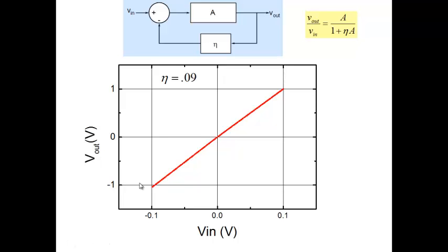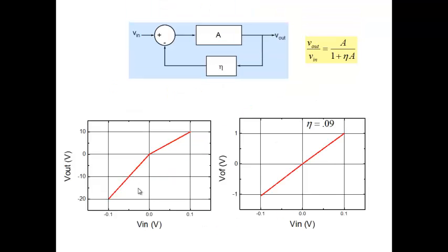How has this happened? So let's put both of them together. How has my overall amplifier with negative feedback become more linear? Highly nonlinear here, A, but with a simple feedback it is highly linear. So what has happened? Look at when you are feeding back the signal: if the gain here is lower, the signal which is fed back times eta is also lower.